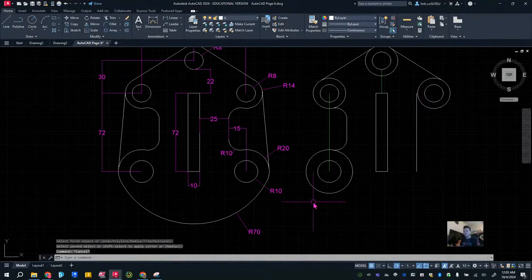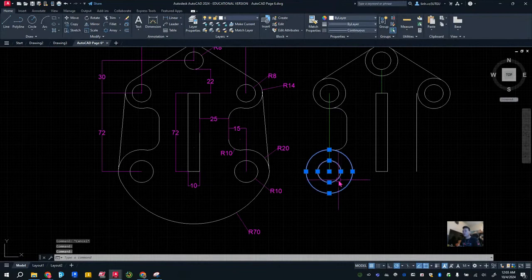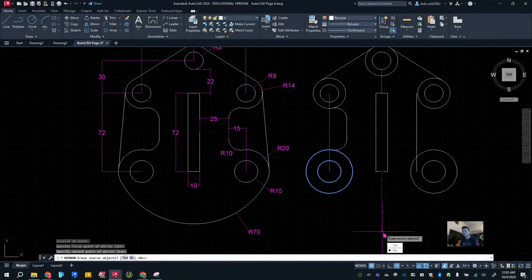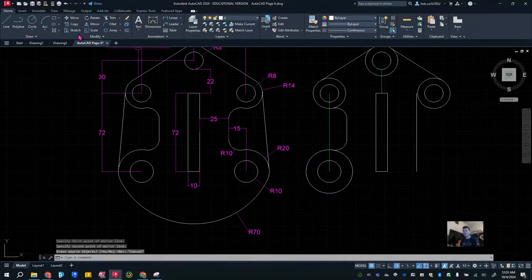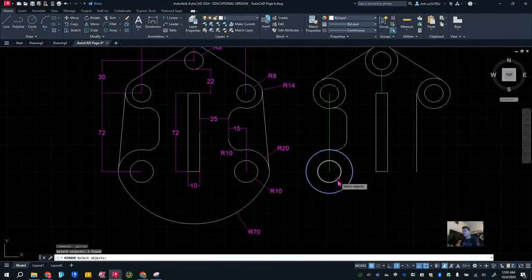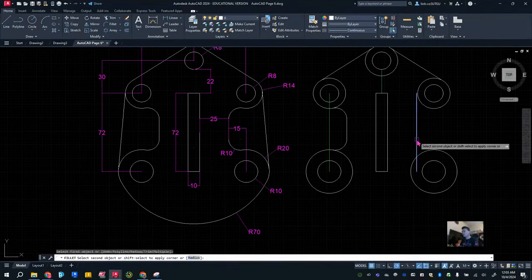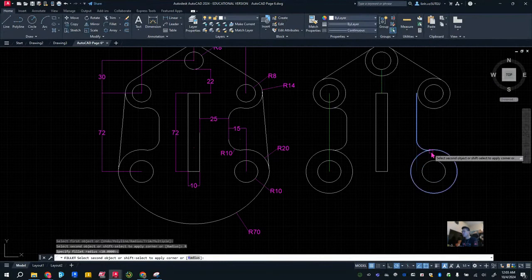All right, what I'm going to do now is I believe I can mirror this over. Mirror those, enter, and mirror those over to the center. Hit this. Mirror 1, 2, and hit enter, and then click there and say no. And then I'm going to go ahead and fillet that one, radius 10, enter, that.